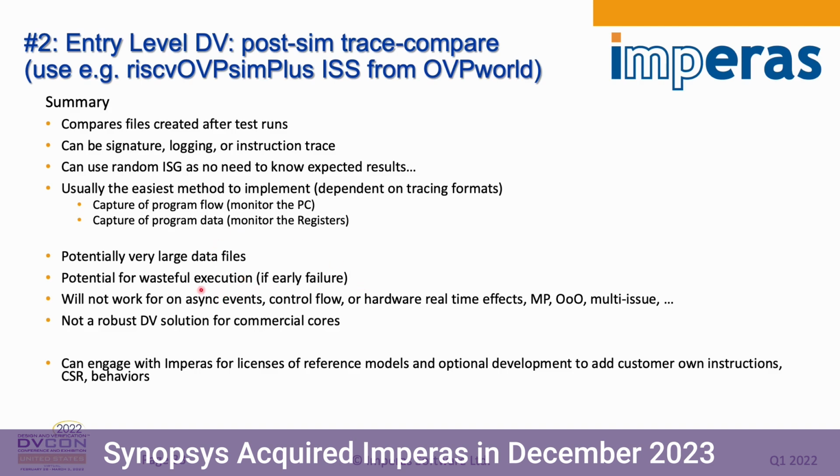And it doesn't work at all well for asynchronous events where you've got interrupts, where you've got in the design under test a pipeline where things are doing things in different orders. Obviously, your reference model is not going to be doing that type of stuff.